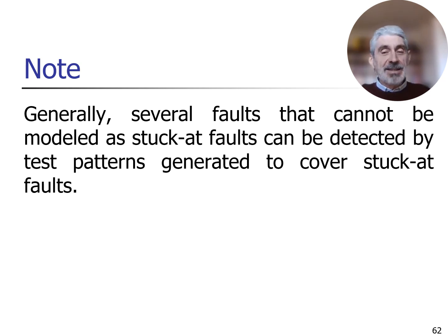So no matter the fact that not all the defects are modeled by single stuck-at faults, it is true that the test vectors generated by targeting single stuck-at faults are very powerful. They are able to detect a huge percentage of defects. Not all, but a huge percentage. And this is another reason why the stuck-at fault model is so popular in practice.